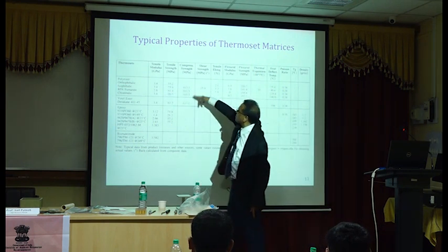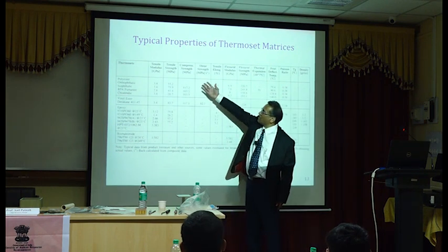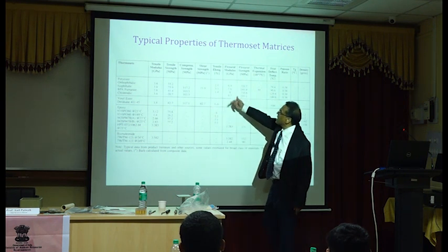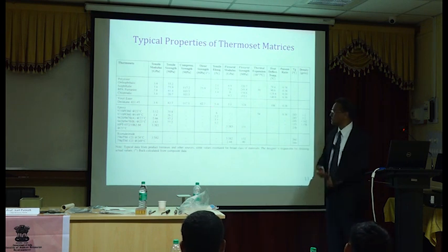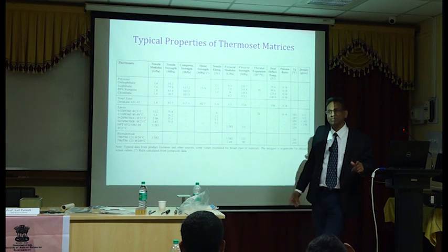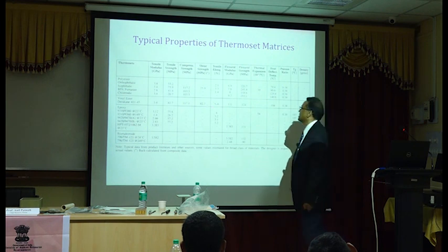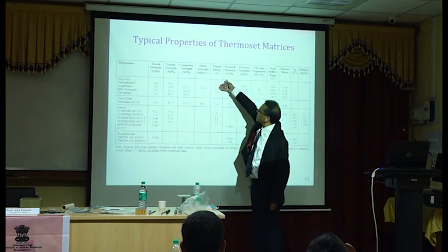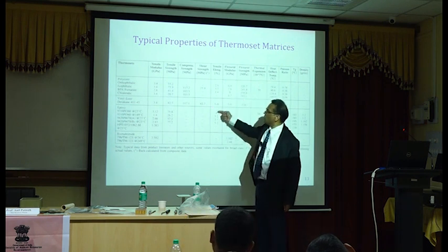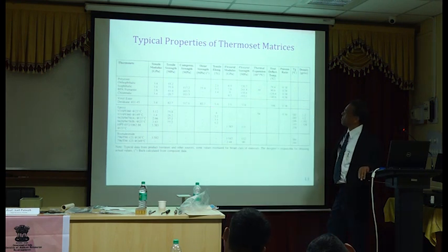Okay? Compressive strength, okay, not all are strong, but a couple of matrices have some compressive strength, which is reasonable. Shear strength is very low, obviously. Elongation, what kind of elongations do you expect in steel? Depends, mild steel, maybe 7-8%, maybe, right? Or at least 6%. So here we have very low, 2%, 1.4. Epoxy may be slightly more, but everything else is low. So that's how I would remember.